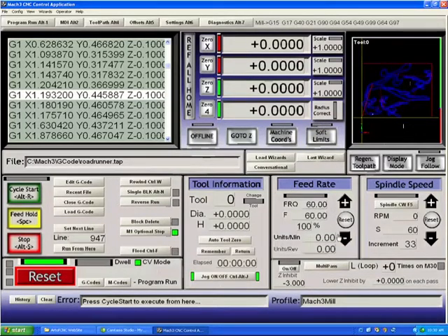We have a feed rate selector. This is feed rate override. We have units per minute and units per rev that are real-time updates as you're moving. Here we have our spindle speed selection. We can turn a spindle on or off. We have spindle speed override, that we can override the spindle speed that was set in the Gcode program and allow the spindle to speed up or slow down. Pressing reset will of course bring it back to 0.